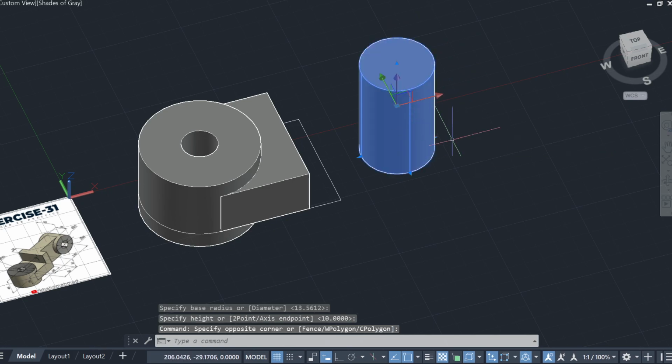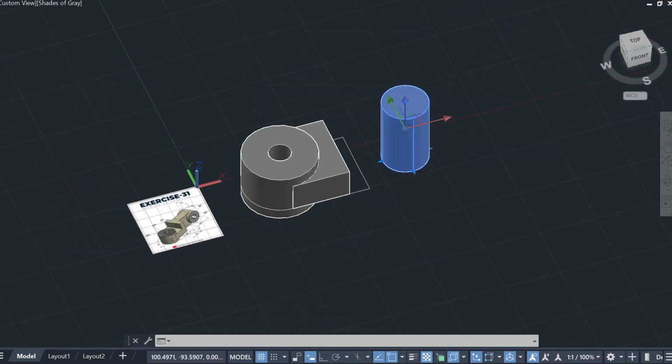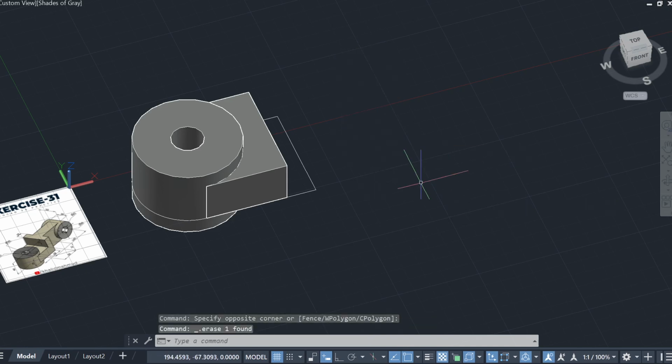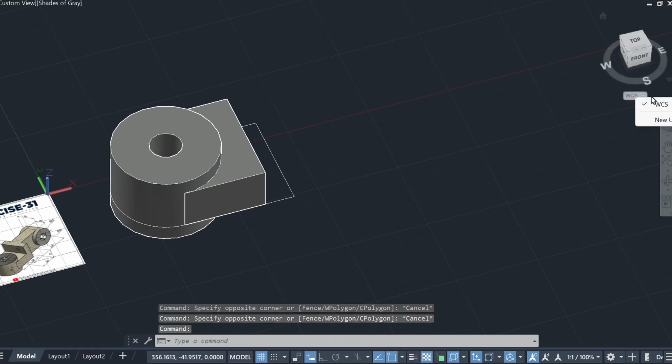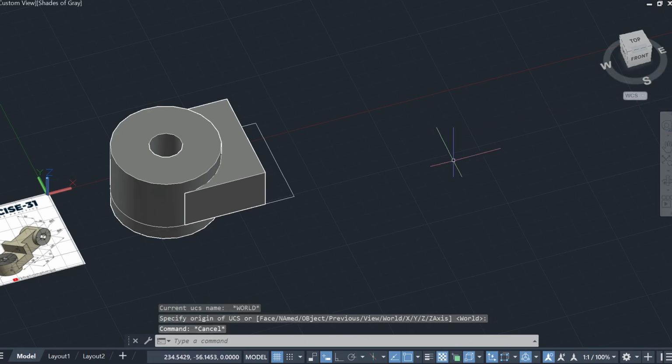Okay? Pero later, for example, if we want to do this horizontal na parang nakahiga na cylinder, no, it will require us to change the orientation of the coordinate system, no. So you need to understand na every time you're dealing with AutoCAD tools, you need to be mindful kung ano yung coordinate system you are currently on, no? So right now, you will know the coordinate system by looking at this drop-down menu dito. So, if I click this, ayan. So, ngayon, naka-World Coordinate System siya. WCS stands for World Coordinate System. So, this is where yung ground natin is the XY, tapos Z, moving upwards. Okay? And you can change the coordinate system depending on what you want.